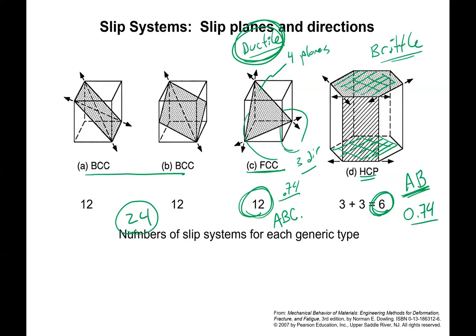What else is going on is there is a friction to move the dislocations that we have to overcome. And so there's a minimum energy or minimum stress, a critical stress, in order to move them. And for the face-centered system, this critical stress is fairly low because we're moving these 1-1-1 planes that aren't sitting very deeply in each other. And in a body-centered system, the planes sit deeper in each other. And so there's a much higher stress needed to move. And so this critical stress is what dominates in the BCC system, making it less ductile than the face-centered. We'll talk a bit more about that in a couple of videos from now.